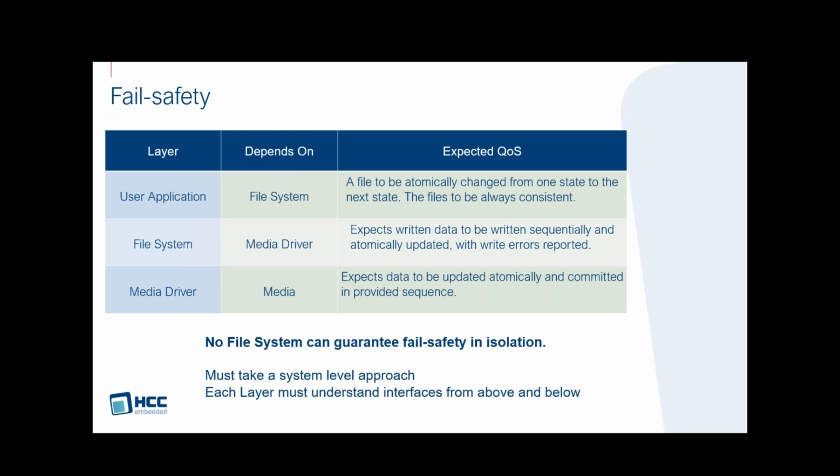If you take a standard Linux distribution and load it onto a board support package provided by a company, how does anyone know that the NAND driver is developed to the standards required of the fail-safe file system under Linux? This is why it is so important to have a system-level approach to fail safety in file systems.